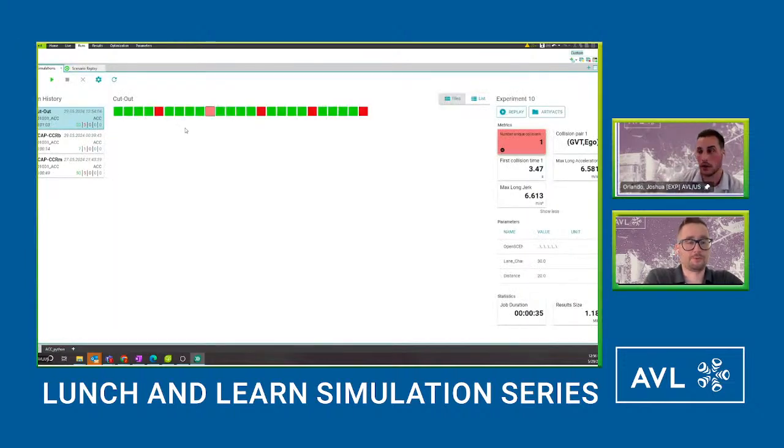So basically, now you would improve your ACC algorithm and rerun it again, right? That depends. Is the scenario that you've executed here inside the requirements that you generated for your ADAS control algorithm? That's something that you have to be aware of when it comes to not only the development of the system engineering, but also the validation and calibration of the system as well. So all that is in terms of your parameters, how you set up the OpenSCENARIO file, and then how you execute.